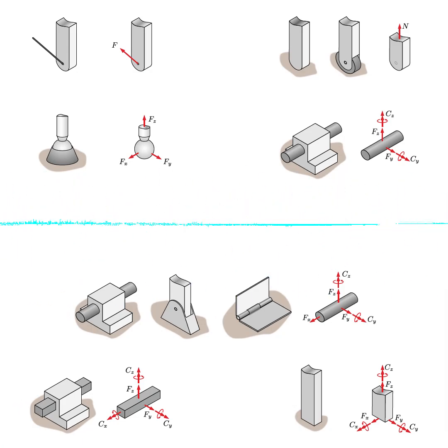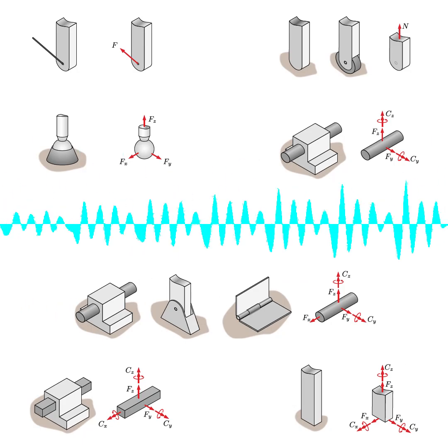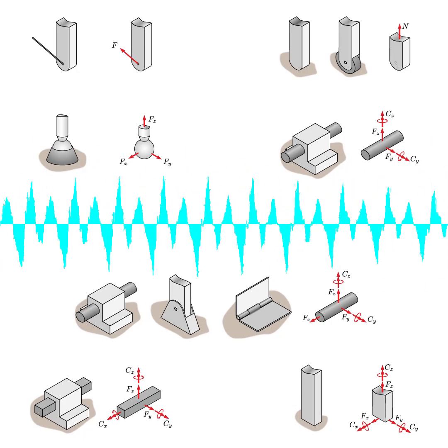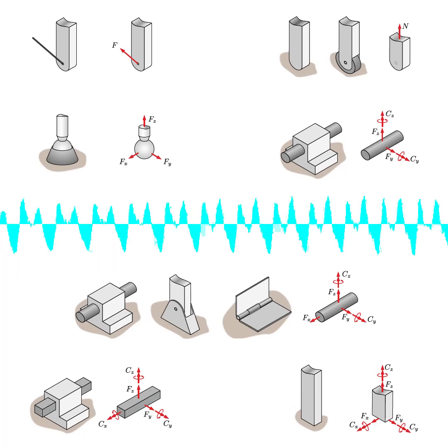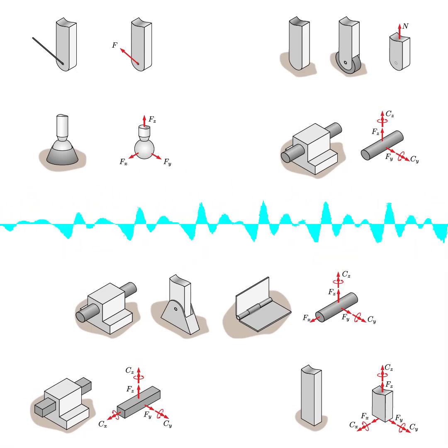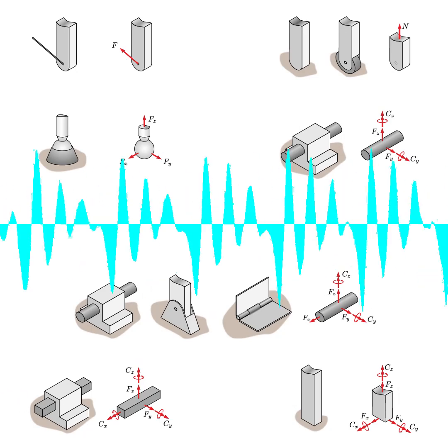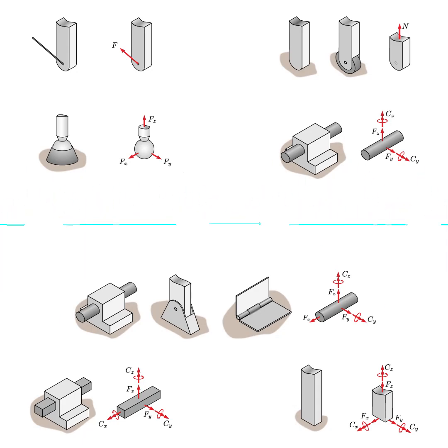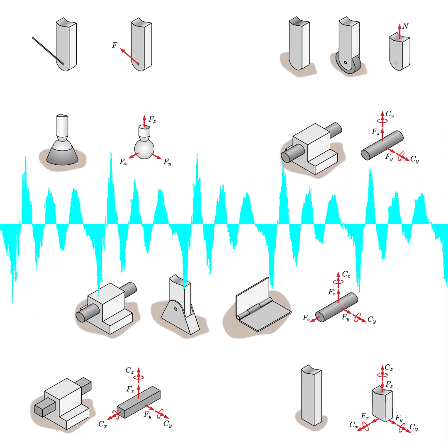Exactly. And then the third check is to look at the lines of action of all your reaction forces. If all of those lines of action intersect at a single point, then the system is likely unstable for rotation about that point. So like a door hanging by only one hinge. Exactly. It's going to swing open. All right, so those are really helpful rules of thumb.